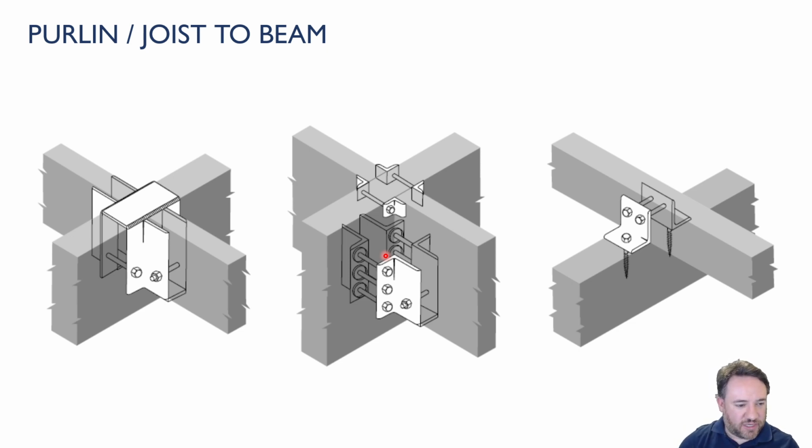So it's almost always better to have a seated connection here. Okay, so I'm bolting to the side of this member. So this is that type of connection that I was just talking about. So it's maybe not totally ideal, but for this really deep member, it's got a lot of resistance, and this load is probably not so high for this member.